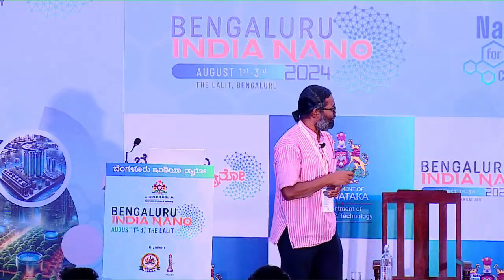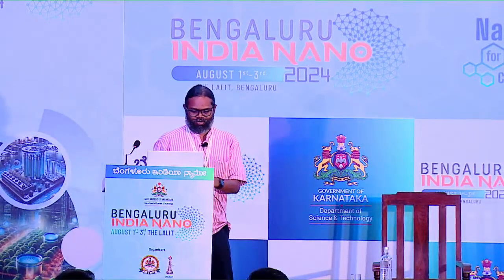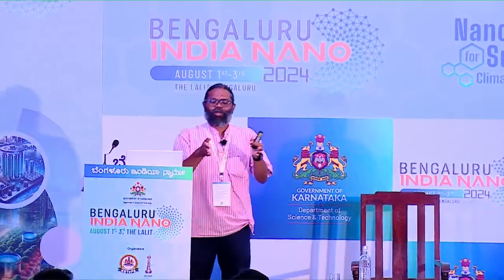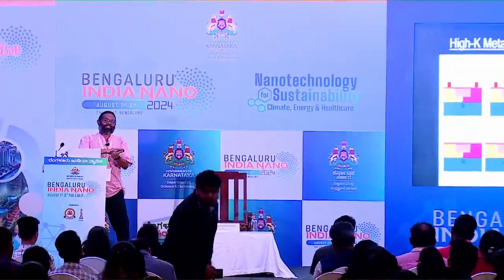So you can start with the polysilicon gate that I have here, right? And then I deposit oxide, again silicon dioxide, and planarize it. I'm just polishing it, and then I expose these gates, okay? And then I can remove these gates selectively, right, by using chemical processes, and it will create these kind of small trenches. And then I can fill this trench with metal, right? And then again polish the metal.